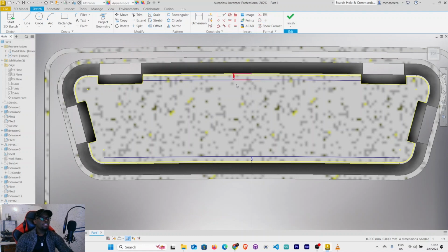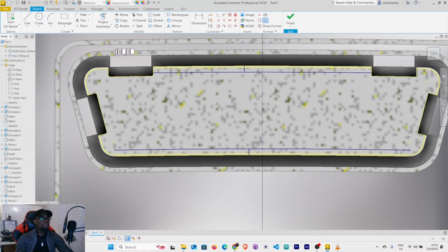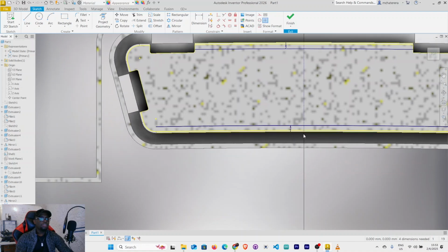Let me move these dimensions. Escape. Let's draw a line of symmetry that is joining this midpoint with this one. Right click, okay. Press escape, make this construction line. I'm going to draw 2 vertical lines. For some reason it keeps snapping onto the midpoint, so let's draw it from here. Just draw it up to here, and then we extend it. Right click, restart. Let's draw another one here.